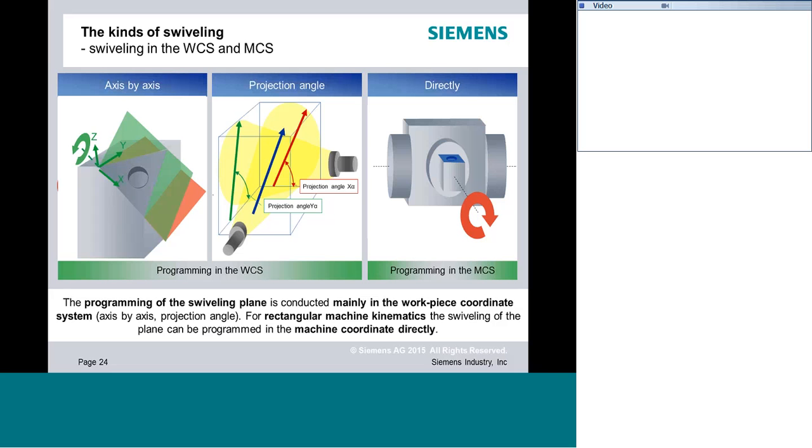Historically, a part program would be programmed, posted, and tethered to that specific machine tool. But between the ability of managing where the rotaries are in space through functions like our tool carrier and Cycle800, and then the ability of positioning values that aren't dependent to a machine tool, this axis by axis, this kinematic independent positioning, we now can have programs, a single program will run on any machine type. Head, table, mix, nutated, doesn't matter.